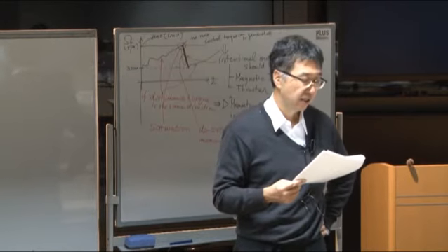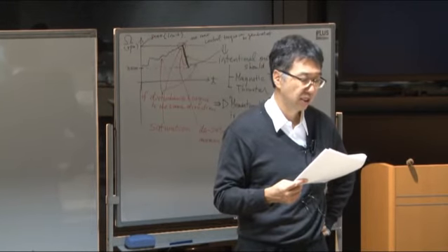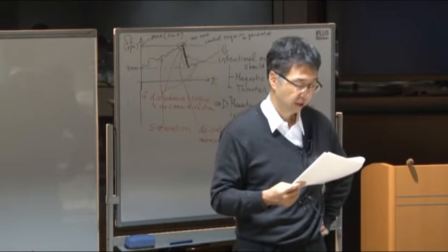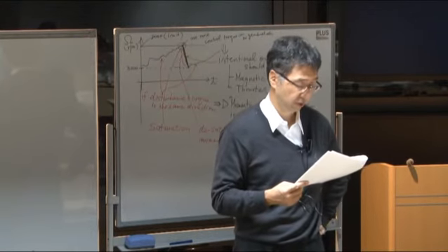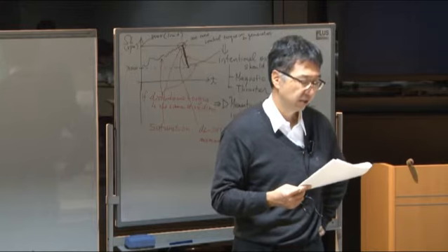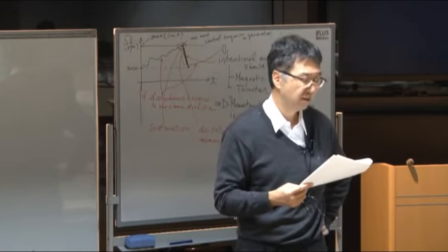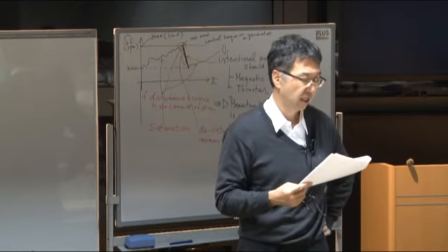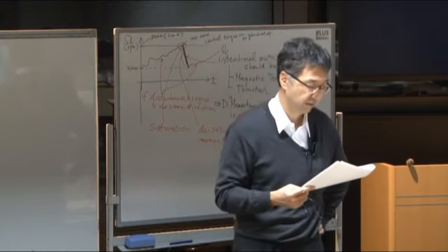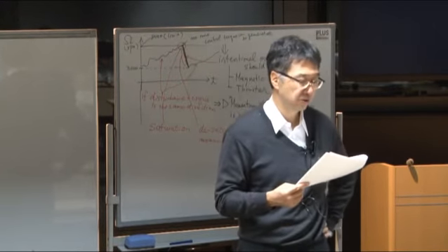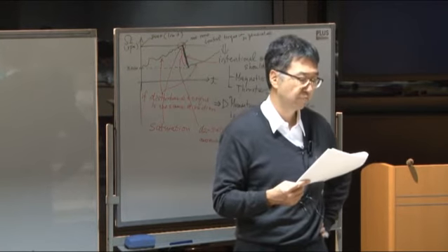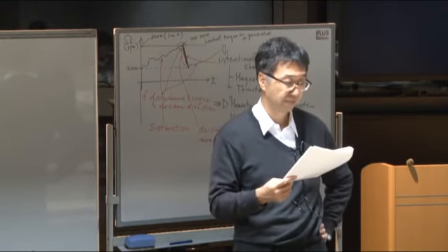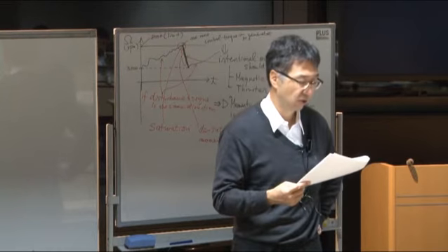Okay, and the one which is dependent on the altitude is gravity gradient. So that is R cubed. It is proportional to 1 by R cubed. So it quickly gets lower if the altitude gets higher. And the magnetic torque is almost the same. It is also proportional to 1 by R cubed. R is the distance from the center. And it quickly gets smaller.